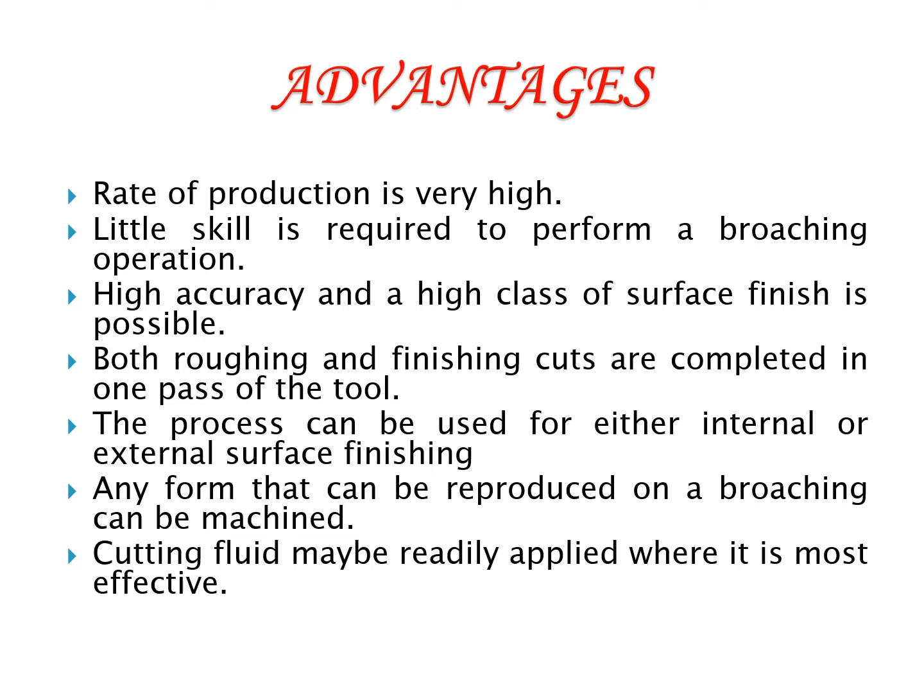So there are some advantages of broaching machines. The rate of production is very high. Little skill is required to perform a broaching operation. High accuracy and a high class of surface finish are possible. Both roughing and finishing cuts are completed in one pass of the tool.